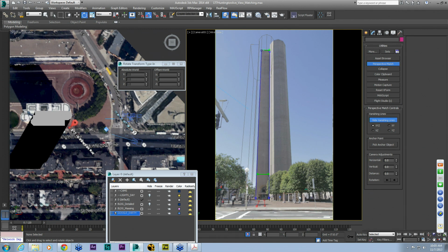If you do encounter an issue where you're seeing the building start to rotate to the side and you're not rolling the camera, things like that, basically when you move one of these axes, that should be the only thing moving. The tell for me when the system's kind of breaking apart was when I would move this and all of the other lines would adjust. And that was sort of a signal to me to just turn off one of the axes and get to a more viable setup where I really only need the X and Y of this one because it's so dead on. And so I was doing that to help clear up that issue.